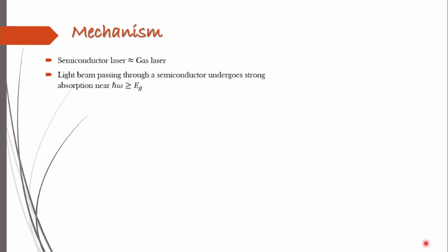So by keeping that in mind and the band structure, we can clearly say that the absorption is due to the interband transition. Interband means in between the valence band and conduction band. So you can remember, interband is nothing but in between the bands, intraband is nothing but within the bands. So here it is going to be an interband transition.